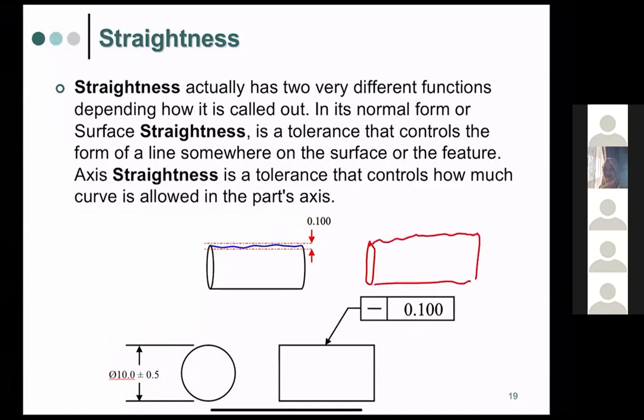What happens if we have something that looks slightly larger than the tolerance? When we want to assemble the shaft with the next part, for example with a hole, maybe this part won't fit the hole. So that's why we have to measure; this shaft should have some type of straightness. And the straightness is actually about 2 dimensions.